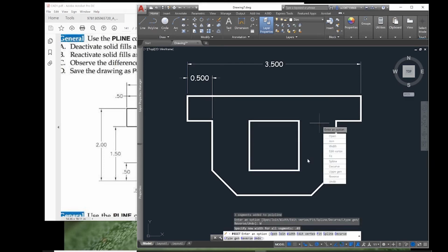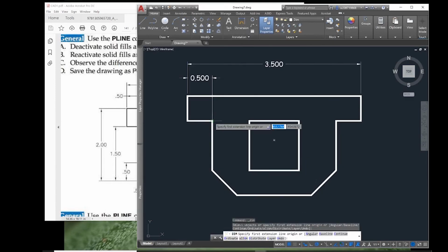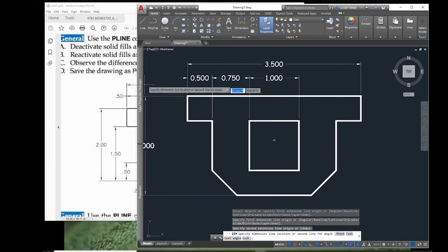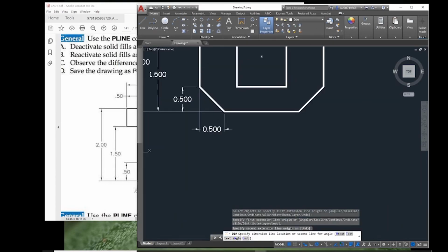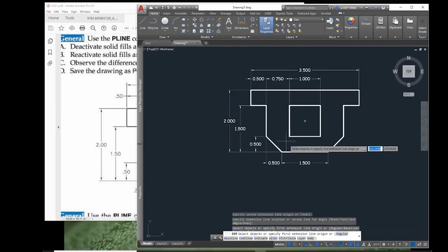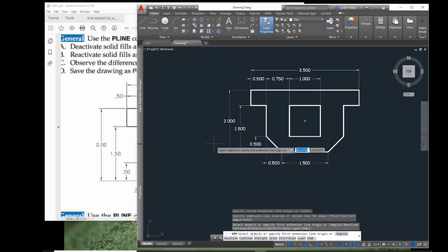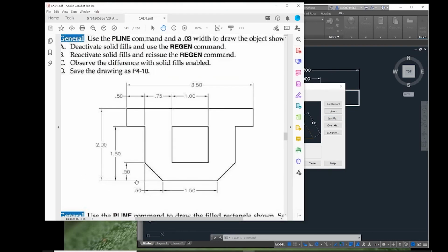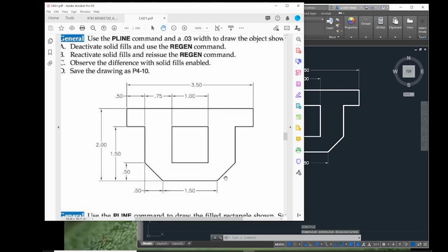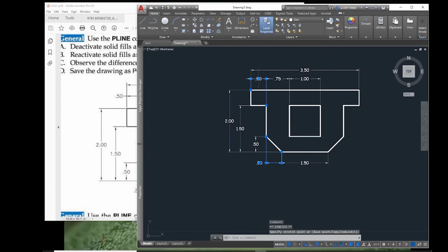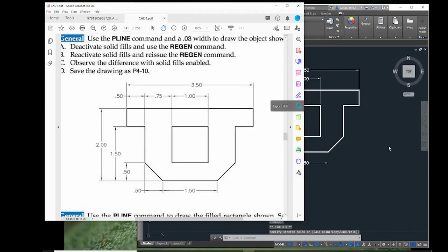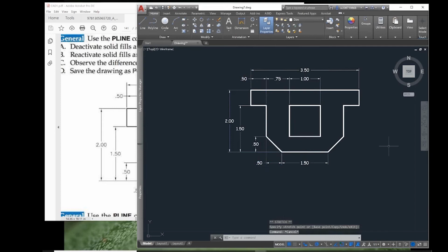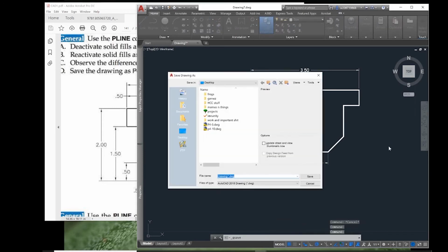Okay, now I'll finish up my dims, and once I change the style to match, we'll be done with this and be able to move on to the next drawing. Looks like all I have to do is suppress the leading zeros, change the precision to 2 decimal places, and move some of these dimensions around. And since I've already been over all that, how to do that in the dim styles, I'll just speed along. Okay, here's the final drawing. Let me know if I went too fast or took too long. Of course, if you have any questions, you can leave them in the comments.